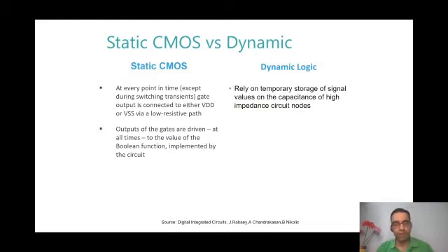What is dynamic logic? Sir, in this logic we use a clock, and we do not use a PMOS network here. We use only NMOS and use a PMOS and NMOS for giving a clock above and below the NMOS logic. Sir, we can do it in two ways. We can have a pull-up network or we can have a pull-down network.